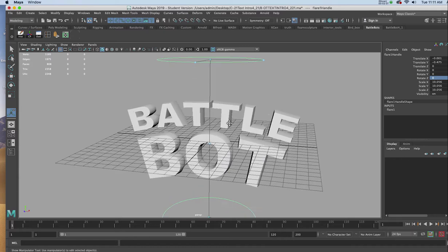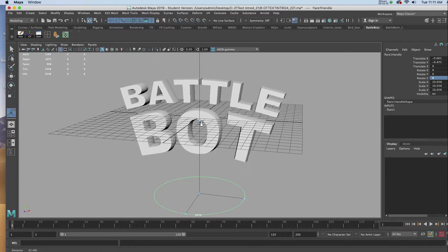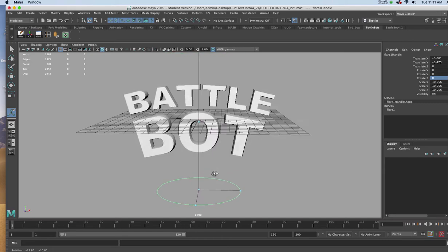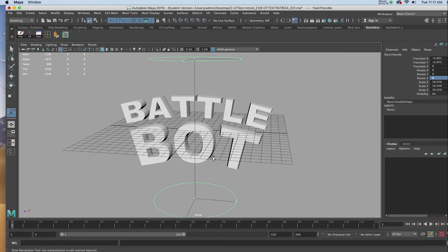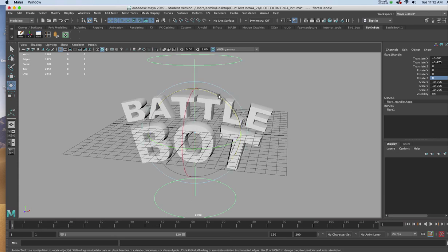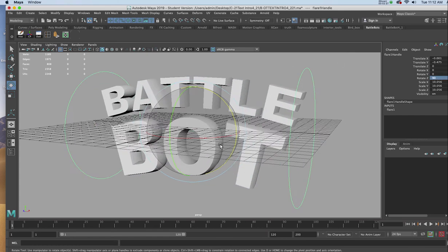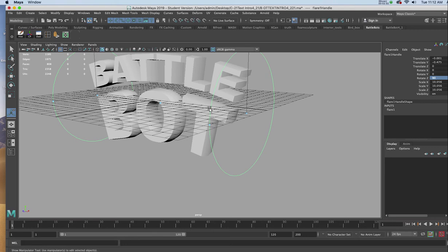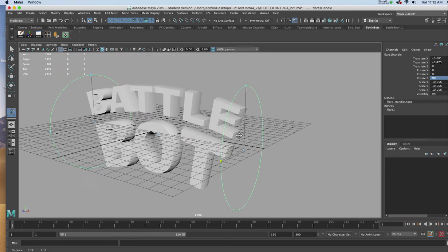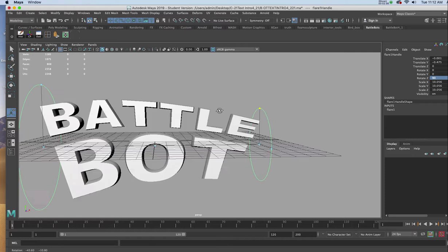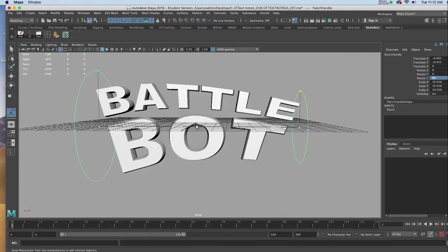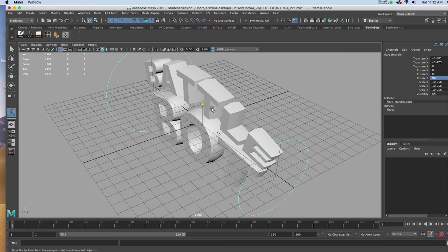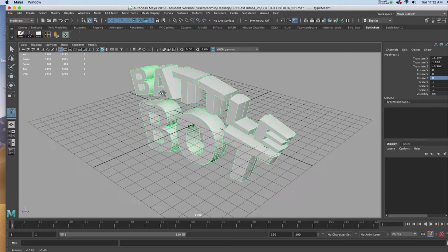And the flare again has some of the same features. There are those 3 diamonds. You'll see there's a number of other ones. But I want this also to start out horizontally, so I'll hit E, and I'll start to rotate it. And once again, in my channel box, I'll put in 90. Now, if I've hit T on the keyboard to edit, I can now go to one of the ends, and I can start to distort that. So I'm going to come up with something like this. And then I'll delete by type history.